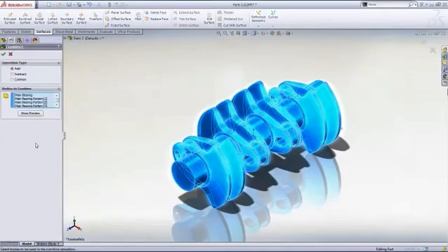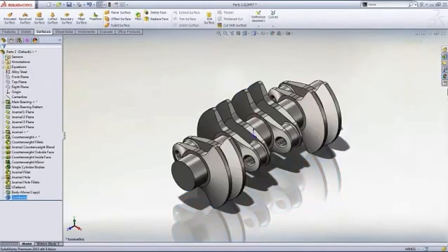This tool allows you to perform different Boolean operations. All we're interested in right now is Add, which merges all the geometry together. And as soon as I did this, the Solid Bodies folder disappeared, letting me know there's only one solid in this file. Before we move on, I want to look at two other tools for manipulating both feature-heavy and imported parts.